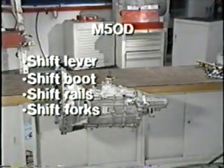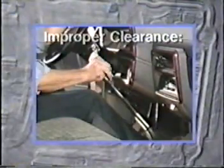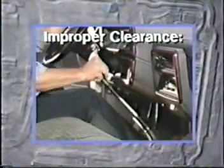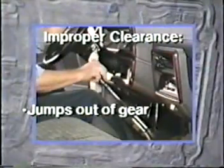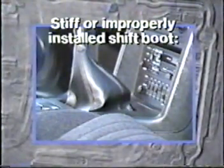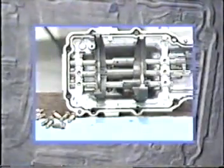One problem you might encounter with the shift lever is improper clearance between the lever and the console. This may prevent completely shifting into one or more gears, usually third and fifth, and can lead to complaints of jumping out of gear or not shifting into a gear. The shift boot can also be the source of shift concerns. A stiff or improperly installed shift boot can make the transmission jump out of gear.